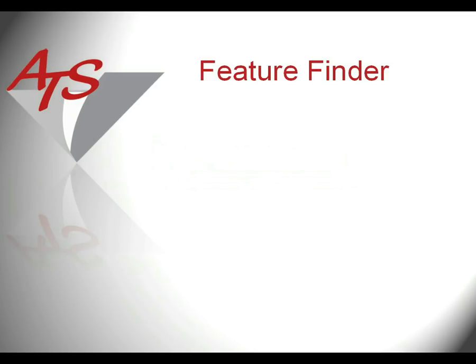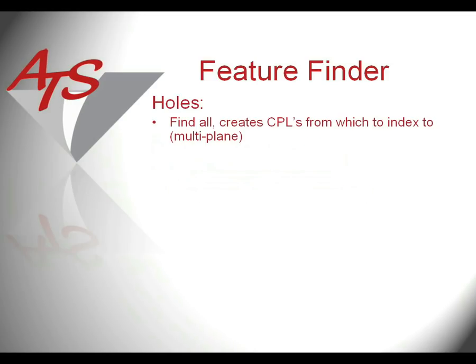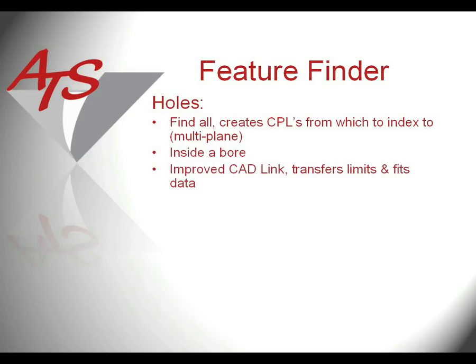In the area of Feature Finder, the hole features have been greatly enhanced, where you can find all holes. This creates CPLs from which you can index to in 3+2 type programming or horizontal machining centers. The ability to define an inside bore hole, the improved CAD link, data transfers, limits and fits from the hole wizards from the CAD packages, Inventor, SolidWorks, Solid Edge, to include taper hole threads or MPTs.